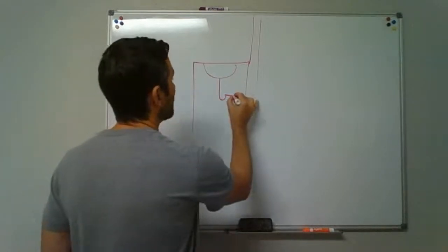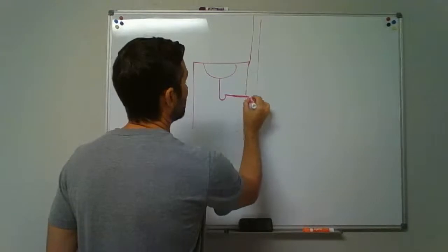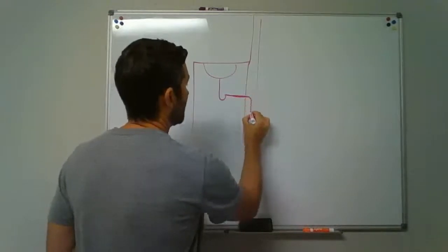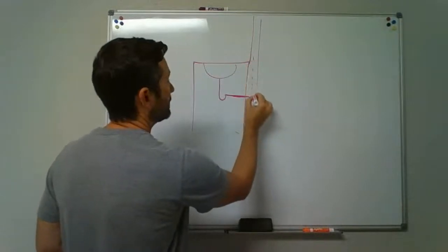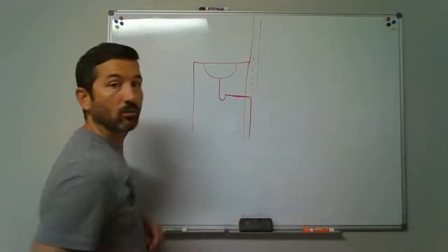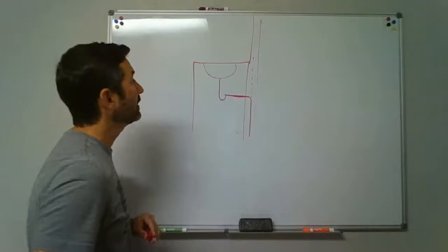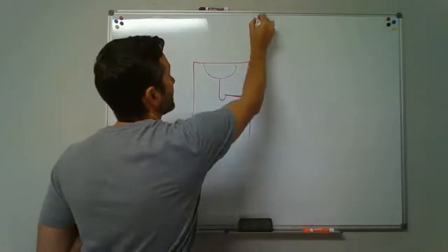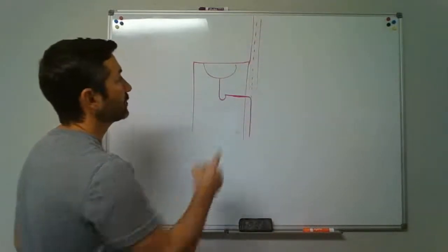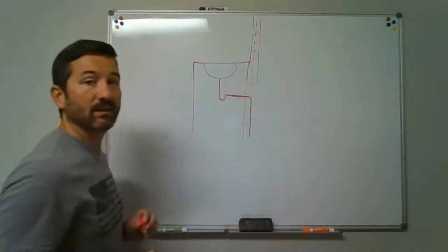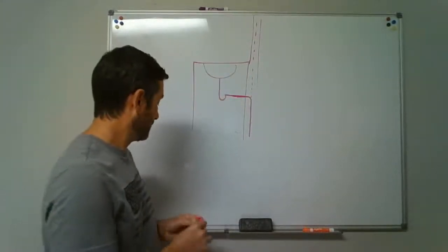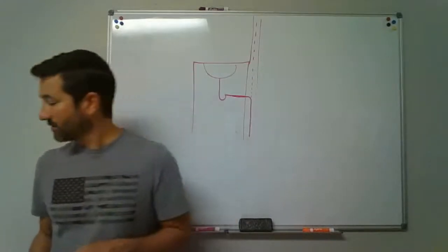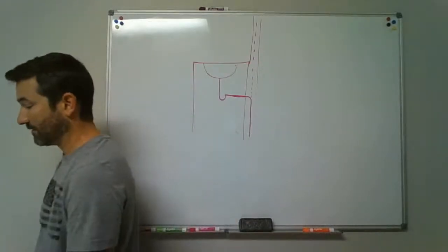Once it heads back into the wall here, we go down with the drain and we go up with the vent. That fitting right there would be a sanitary T, and the dashed line represents the vent going up. So we've got one trap with one vent for that. That's an individual vent. It says all our fixtures in the house are allowed to be individually vented.